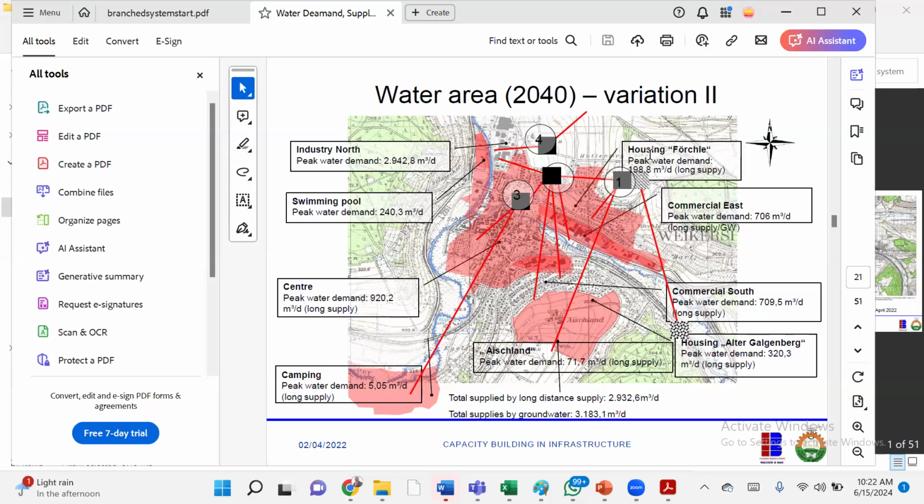Okay, so somebody says 75 mm. Yes, of course, that's nominal. But in the chart, you get something like 50. But I say it again, in water reticulation design, in general infrastructure design, it is better to overestimate than to underestimate. If a 1 meter pipe is enough and I provide 1.2, it is not bad. But it will be bad if I provide 0.8. That's the rule of thumb.